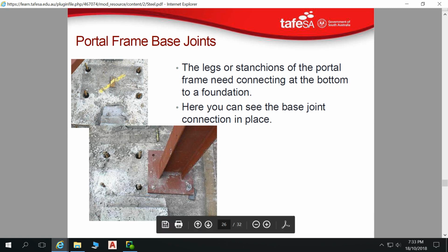Unfortunately, you can't get nearly the same pull out strength with a Dynabolt. So Dynabolt, 1.5 kilonewtons of restraint or something like that. It's very little. And particularly, I look at these and go, oh, yeah, M10 Dynabolts, 50 millimeters deep.